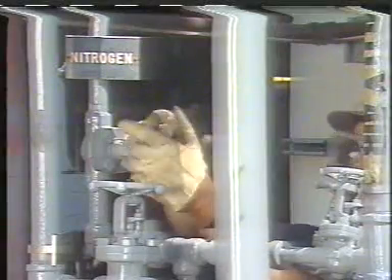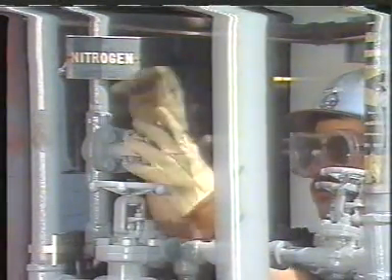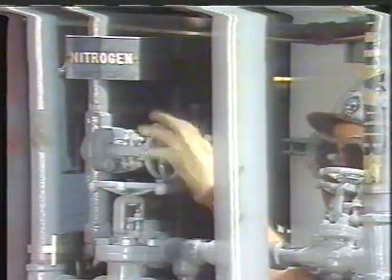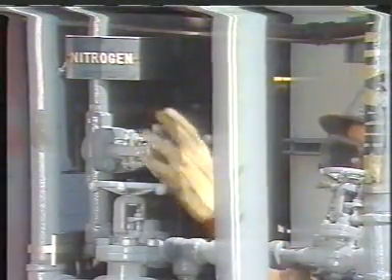Because pressure decreases as temperature is reduced, there's always the possibility of a vacuum occurring in the tower while it is being shut down. If a vacuum occurs in a tower that is not designed for vacuum operations, the column could collapse. To prevent this from happening, an inert gas like nitrogen is introduced into the tower to maintain a positive pressure.